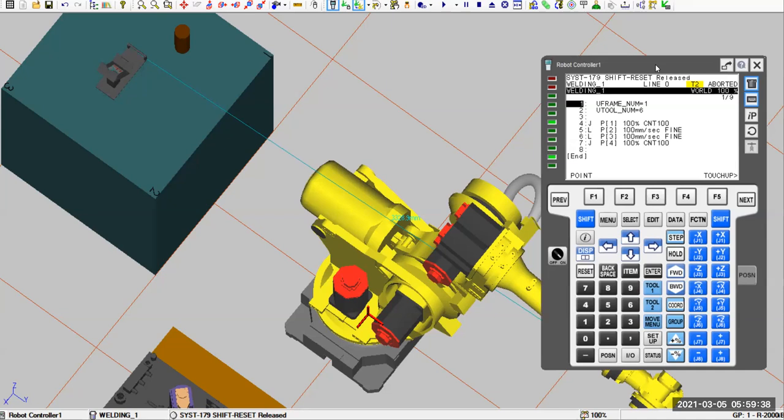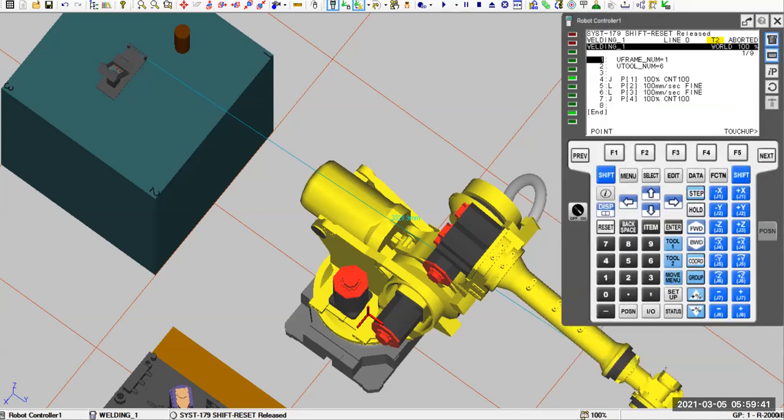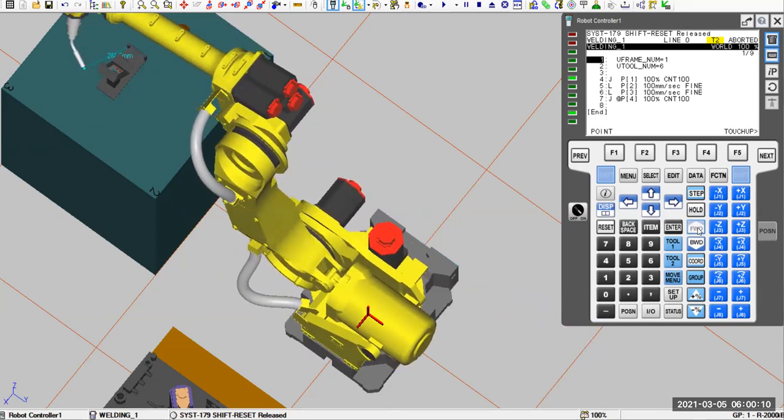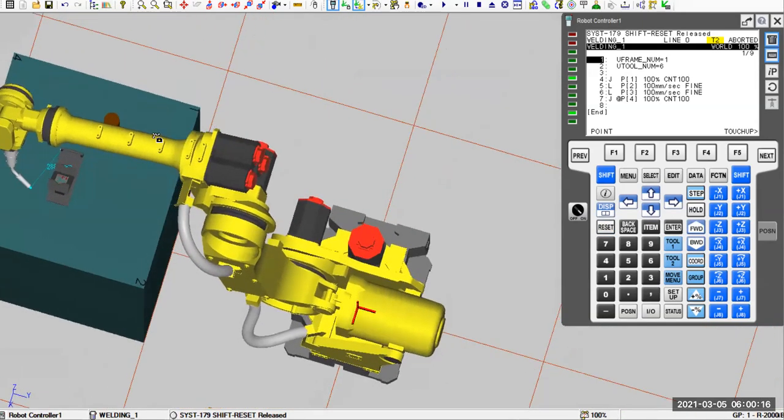So that's what I'm saying. All right, magic happened. Before, the robot was running the old program. Now, if I shift forward, run the program again, the robot controller will get the new data we just entered on user frame number 1. The tool frame doesn't change, so we should get the robot welding from this corner to that corner again, exactly the same as before. You can see the robot start there and then weld and finish. Is it that exciting? I think that's very cool.